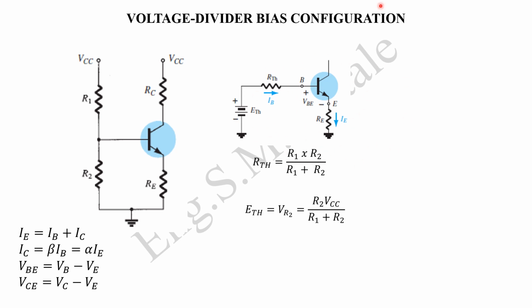So from here, if you have to analyze an equation, you will realize that you've got the voltage which is ETH. This one will drop across these parameters. So there will be a voltage drop on RTH, which we are calling IB RTH, which is this one. There will be a voltage drop there, which is VBE. This is the one you're having. And you're going to have the voltage drop on the emitter. The voltage drop on the emitter is that. So you have this, and you can easily do your equations. So this is our analysis, getting this path.